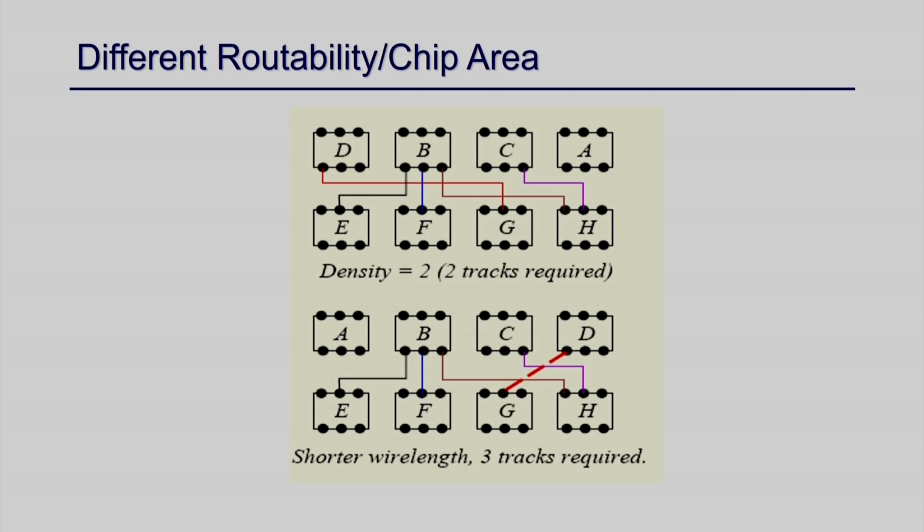And also sometimes, when you try to make the connections, you have to see that two connections cannot cross in the same line. So, if you plot the blocks like BC, CA and EF, GH, then to make all the connections you need only 2 tracks, right. You can make a connection like this, and another connection that is not overlapping, so they can be put in the same track, and this connection can be put in another track. So, you need 2 tracks, right.